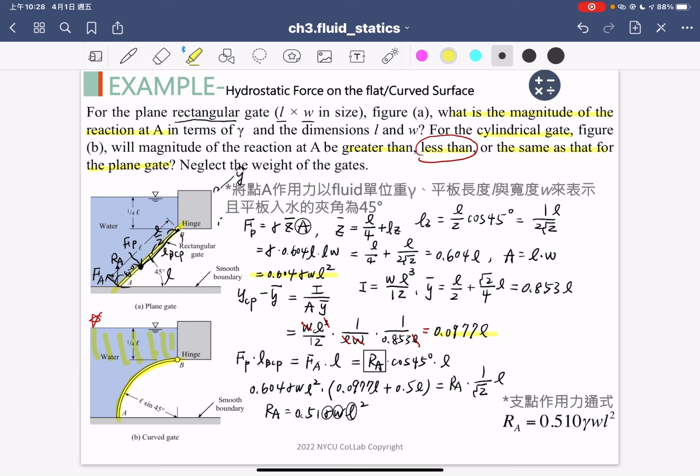But in condition 1, the liquid loading above is larger compared to condition 2. That's why we don't need to compute again, because we can directly see the two conditions above the gate, how much liquid loading we have. So we just pick the smaller liquid loading one, and this is our final solution.